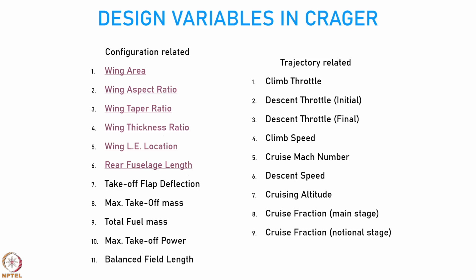Now, I told you that the best profile available for minimum fuel consumption is just a sawtooth. You climb to the destination, and then descend. But you cannot do that in actual operations. There are two main reasons. One is that ATC would like to monitor you, and they are happy if you maintain a constant altitude. So, because of ATC requirements, you might be forced to fly at some altitude lower than the optimum, just so that they know that you are in this particular location in straight horizontal flight.